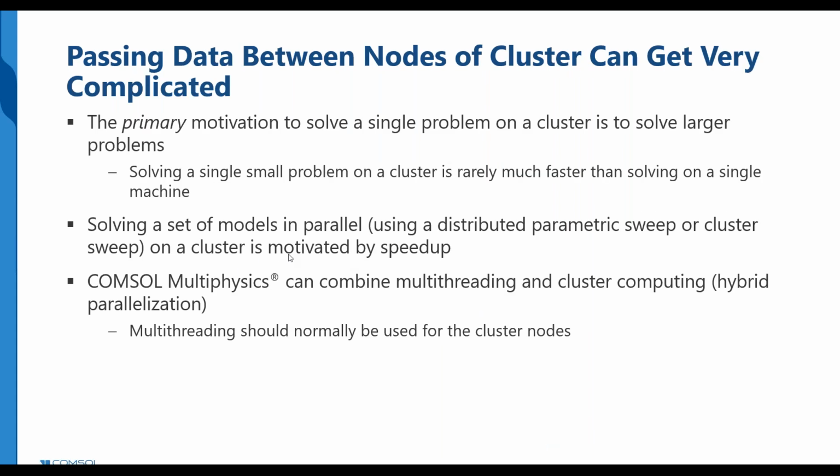So communicating between those processors can be very complicated, and the motivation to go to a cluster is not primarily to solve the problem faster, but to reduce the peak memory use for any of these cluster nodes, so that I can solve a larger problem. Basically, when you run out of memory, when you have done all the things on my previous slides, and you still want to solve the big size problem, then a cluster can be a solution.